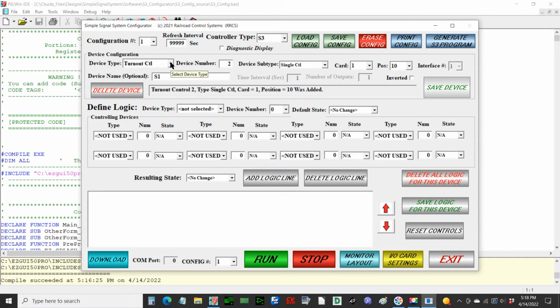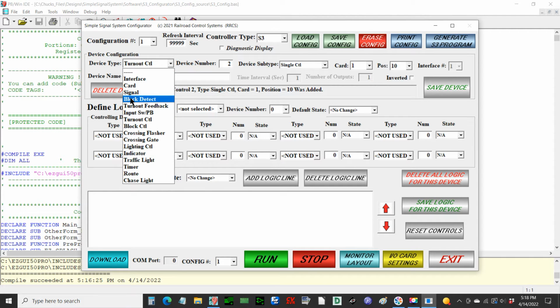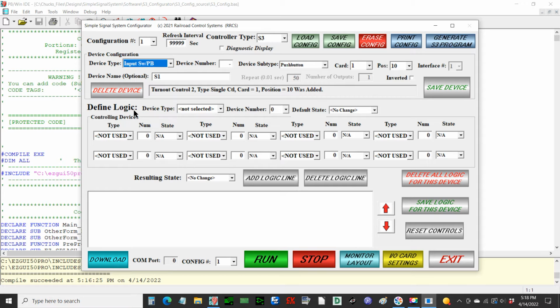Now I want to create the push buttons that we're going to use here. I'm actually going to use a different type of push button for this. For input number 1, to simulate block 1, I'm going to use a push on off button. And the reason for this is so we don't have to try to hold down 3 or 4 buttons here simultaneously. We can operate these and we can set them on and set them off by pushing the button once or pushing it again.